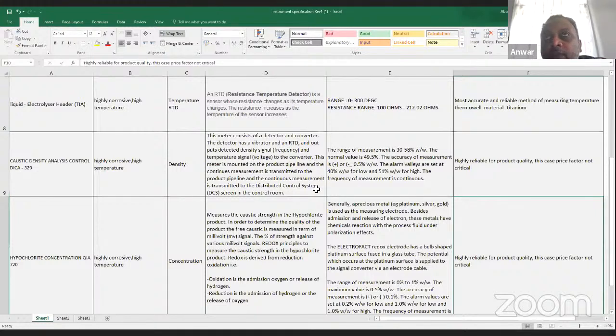Is it the purity of the vapor that you are going to measure, meaning that the vapor has less moisture? Then you need to have a good moisture meter selected for that particular stream. So normally, if you are talking about two-phase, you will have this kind of decision making when it comes to the selection.